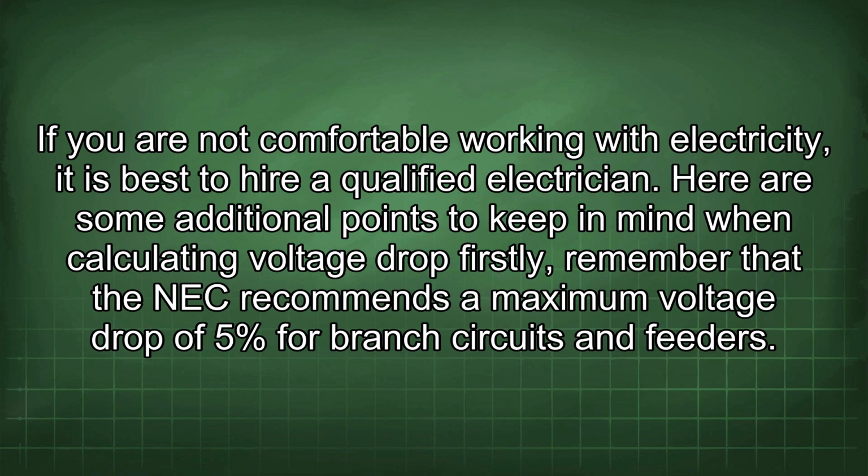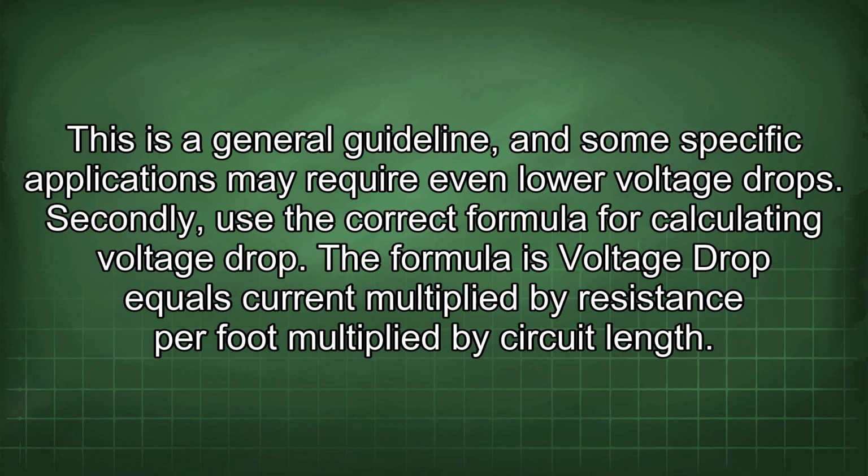Here are some additional points to keep in mind when calculating voltage drop. Firstly, remember that the NEC recommends a maximum voltage drop of 5% for branch circuits and feeders. This is a general guideline, and some specific applications may require even lower voltage drops. Secondly, use the correct formula for calculating voltage drop.